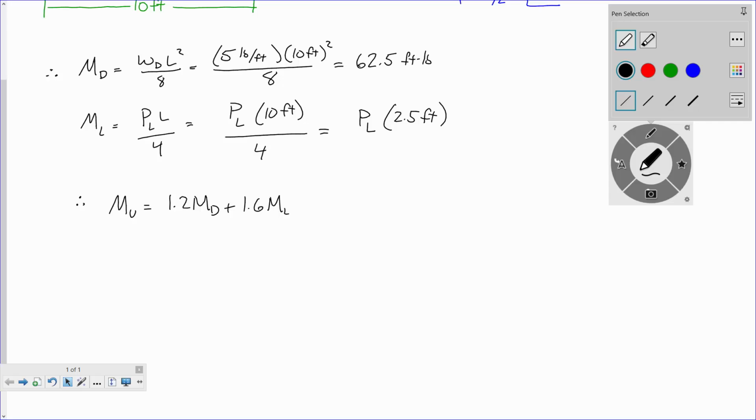Yes, sir. Does it state specifically in here, are there any assumptions that we just believe we don't have to take into account the weight of the beam? That's another good point. Unless stated otherwise, you probably want to at least consider it. But where it is concrete, we weren't provided with a self-weight, like a unit weight of concrete. You can assume like 150, that's a common assumption, but it is that, an assumption.